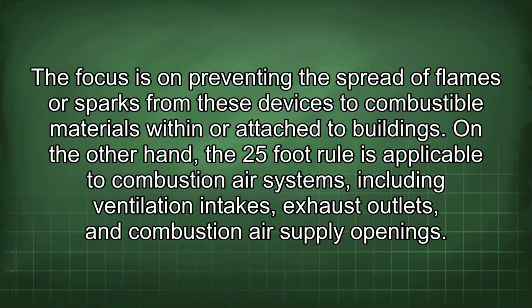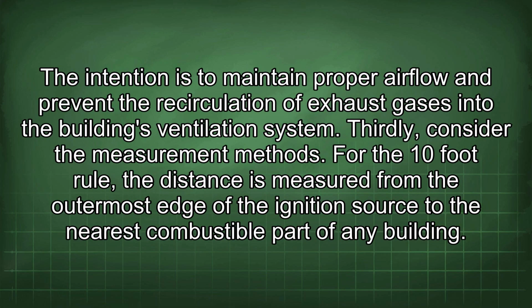to buildings. On the other hand, the 25-foot rule is applicable to combustion air systems, including ventilation intakes, exhaust outlets, and combustion air supply openings. The intention is to maintain proper airflow and prevent the recirculation of exhaust gases into the building's ventilation system.